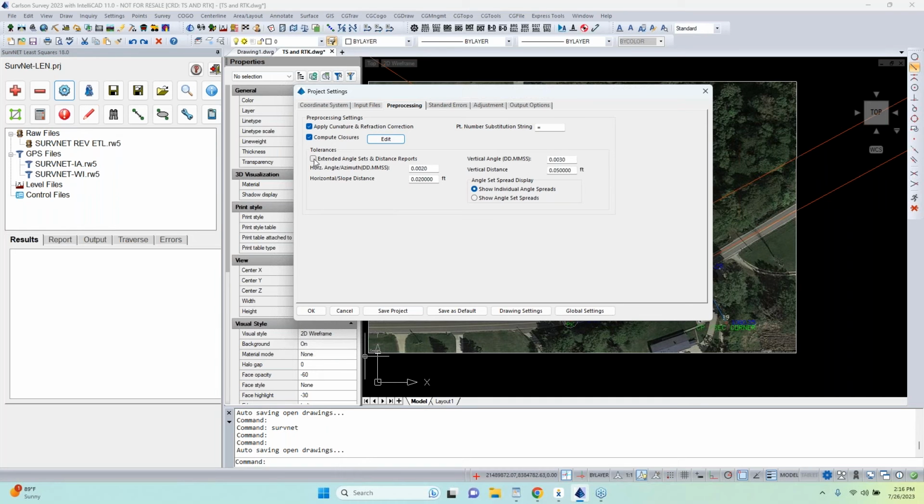We've got some tolerances where if we want, and you'll see when we run the adjustment, that if there's a tolerance that is exceeded in the raw data, like if you measure slope distance to a couple of points more than once, and this tolerance of 200ths is exceeded, it's going to flag that and just put it in the list. It's really nice. It's at the beginning of the report. If there's something really crazy where you've got a big discrepancy between 2 measurements, it's going to pop right out at you. But I don't want to see every single one of them, so I try to set these to reasonable values, a couple of hundredths, maybe even more than that, and just report really big outliers. And you can always adjust these if you want. After you do an adjustment, you want to say, I want to change my pre-processing so that it helps you isolate where you might have some problems. So we can do that for the horizontal angle, the distances, and the vertical angle.